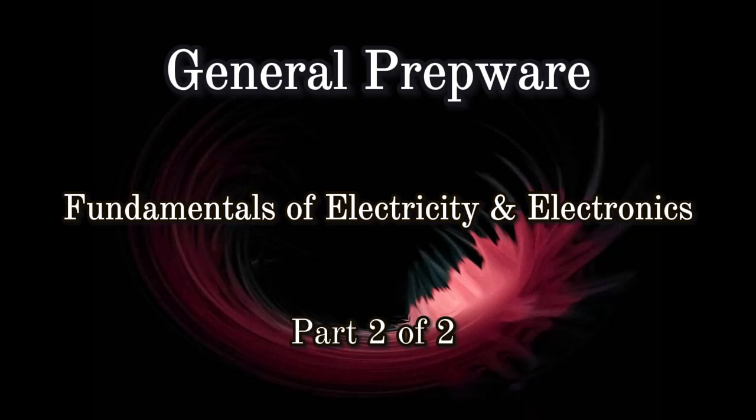Which of the following best describes the operating principle in a nickel-cadmium battery installed in an aircraft? To completely charge a nickel-cadmium battery, some gassing must take place, thus, some water must be used. An increase in which of the following factors will cause an increase in the inductive reactance of a circuit? Inductance and frequency.